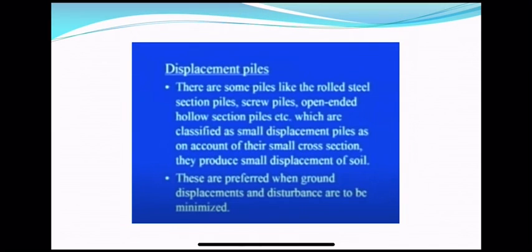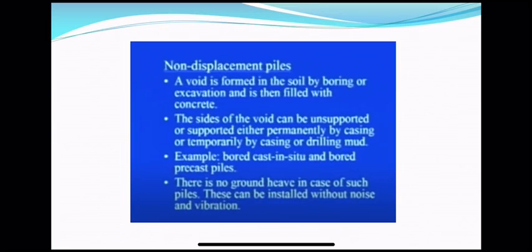So now let us see some of the features of non-displacement piles. In displacement piles, disturbance is caused in the surrounding soil while driving or installing the pile. However, in non-displacement piles, a void is formed in the soil by boring or excavation and is then filled with concrete to form the pile.